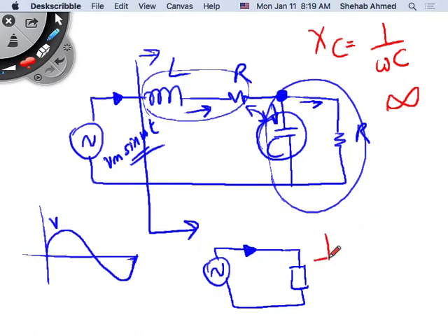So if you have a DC source here, and you have an equivalent impedance that looks like a capacitor, RC, whatever, but it's more like an RC type circuit, right? So the equivalent is more capacitive than inductive. In that case, if you have a switch here that you close initially, there will be an initial transient if the capacitor is not charged, right? So yes, there will be some exponential rise in current, right? Or exponential rise in what? What will exponentially rise? Actually, not current.